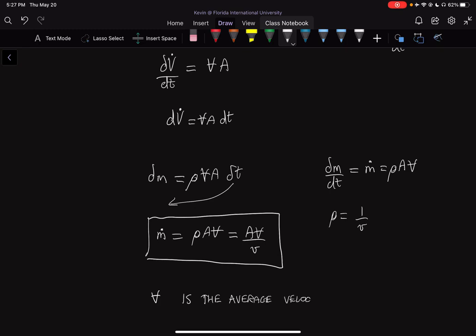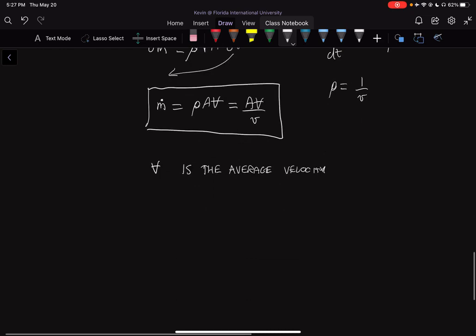So sometimes velocity, and in most cases, velocity through a pipe is not always uniform throughout. You might have flow that is faster through the middle of the pipe. So if I draw a pipe here like this, and I show you a velocity profile of the flow, sometimes the velocity profile looks like this. So you could have a case where the velocity is not uniform.